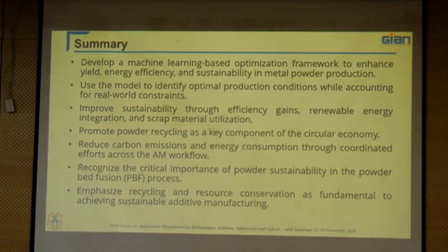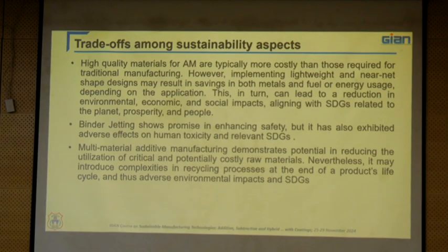But all these things cannot be applied freely; there should be a trade-off between the sustainability aspects and additive manufacturing. Even with all the quality powders in terms of the PBF process, the binder jet process, or multi-material additive manufacturing, it will be difficult. If you go with copper or nickel based alloys, or copper with stainless steel alloys, the copper and steel will be contaminated. Then again we have to separate them out by density and by chemical aspects. Then it will be a more tedious process for the sustainability of such functionally graded materials and multi-materials. There is a trade-off between sustainability and additive manufacturing.